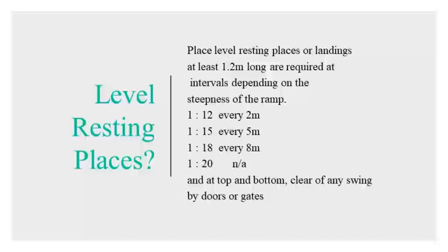The general limitation on the use of ramps is not just that there is sometimes a legal limit on steepness, but also that longer ramps need intermediate level resting places. The steeper the ramp, the more frequent the resting places. The rule of thumb for the length of ramp before a level resting place is required is shown in this table on the screen. Level resting places reduce the effective slope of the ramp.